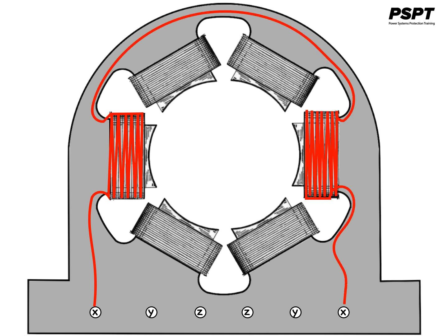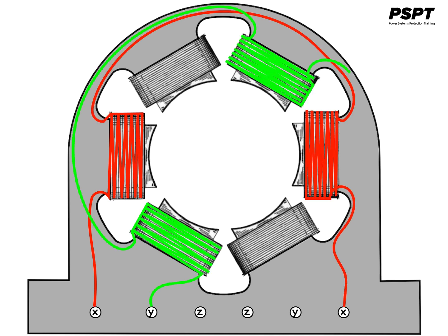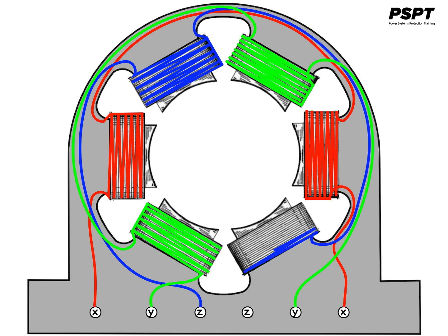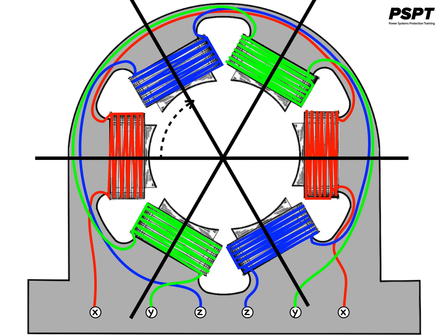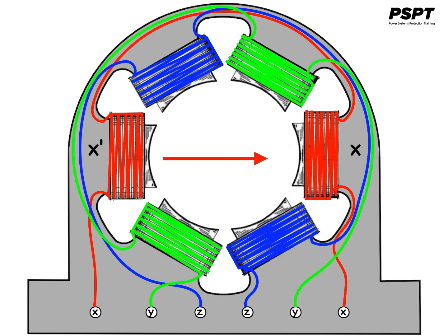In this example, a three-phase machine stator has 3 sets of coils, mechanically spaced 120 degrees apart. Each coil is split in half, creating 2 poles, essentially a north and south pole, which I have designated X-X primed, Y-Y primed, and Z-Z primed, and when energized will produce a magnetic field pointing in the direction of the unprimed half of the coil.